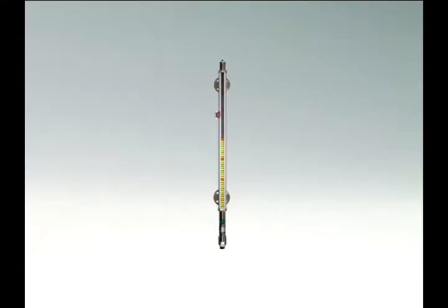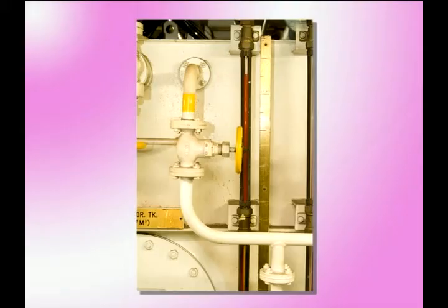It is always necessary to know how much fuel oil remains, and whether or not the proper quantity of water has been supplied to the boiler. It is also necessary to know exactly how much crude oil, or LNG, has been loaded or unloaded. For these reasons, level meters are installed in most vessel tanks. The level meter is usually a glass tube connected to the side of a tank to allow for measurement by sight.